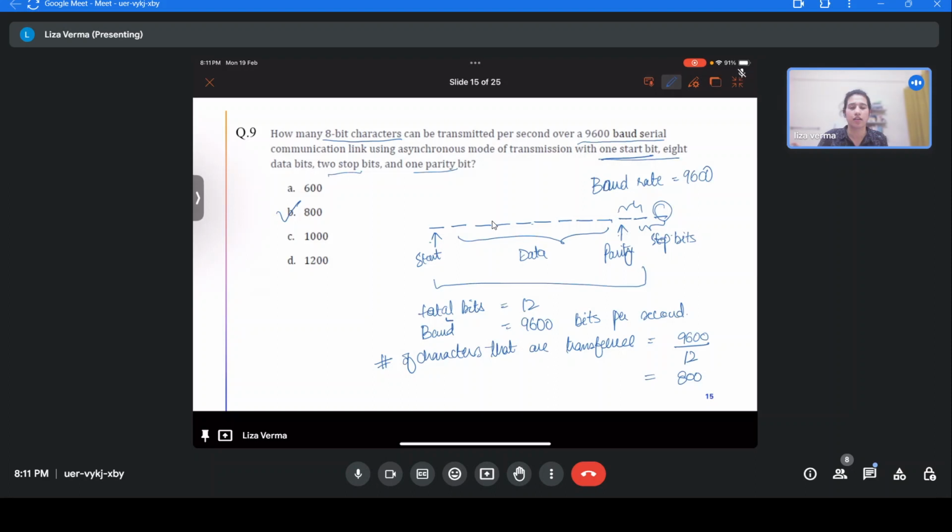At the transmitting end, you can send just the 8 bits, but the receiver has to know when your data is starting, right? Normally the serial line at the receiver is high, and when the start bit goes low, this is considered the starting of the data.